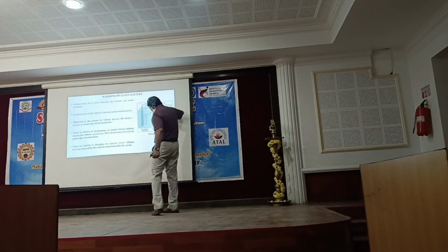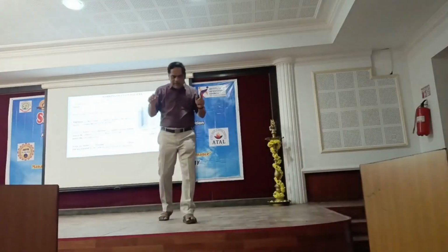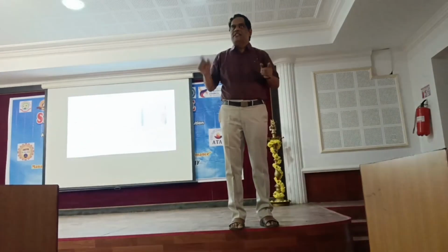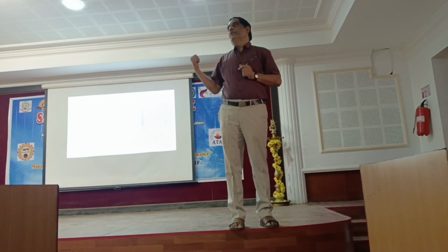Ultimately, why should I bother about this movement of the ion? If you ask me why I should care about transport properties, it is fundamentally connected to how fast I can charge and how fast I can discharge the battery. It is fundamentally connected to the movement of ions back and forth, what speed they can move, and what charge they carry.